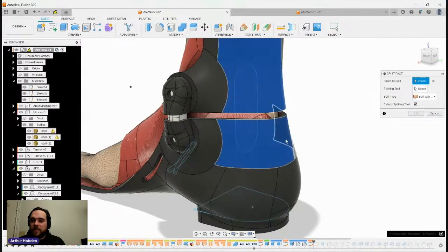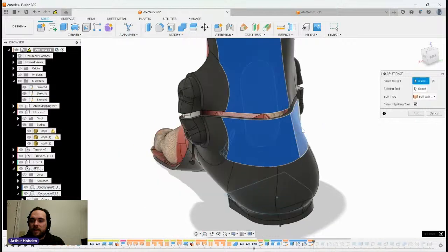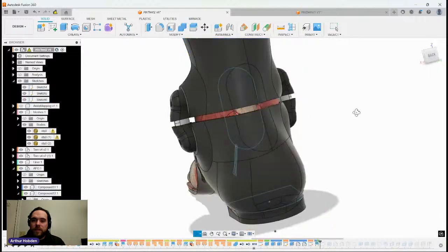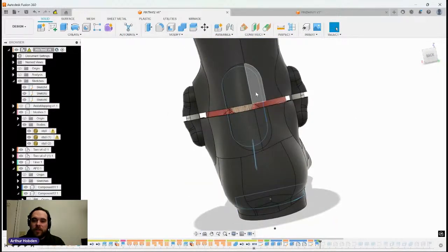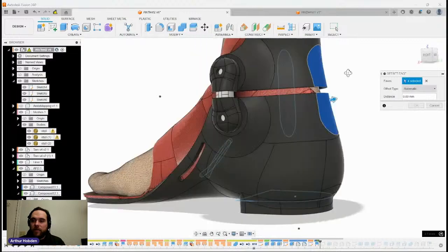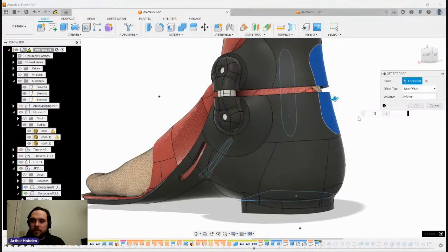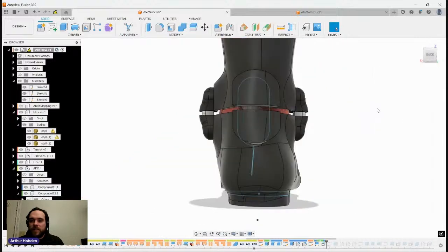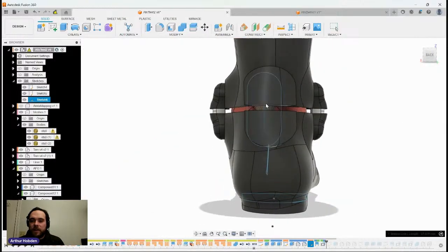We're going to split this face and this face and this face with our sketch that we just made. And now when we have that, we can hit Q on our keyboard and hopefully just bring this out by, as a new offset, 10 millimeters. Hey, that looks like it'll work. And again, if we don't like where that is, because that does kind of cascade off the back, we can move this around and it should update just fine.